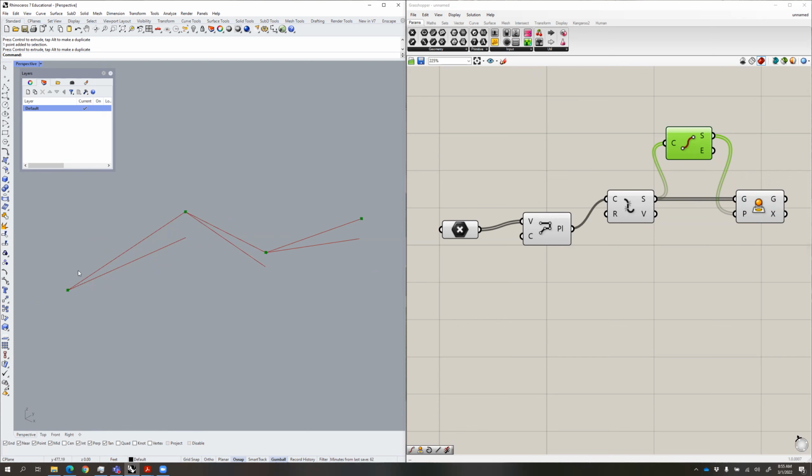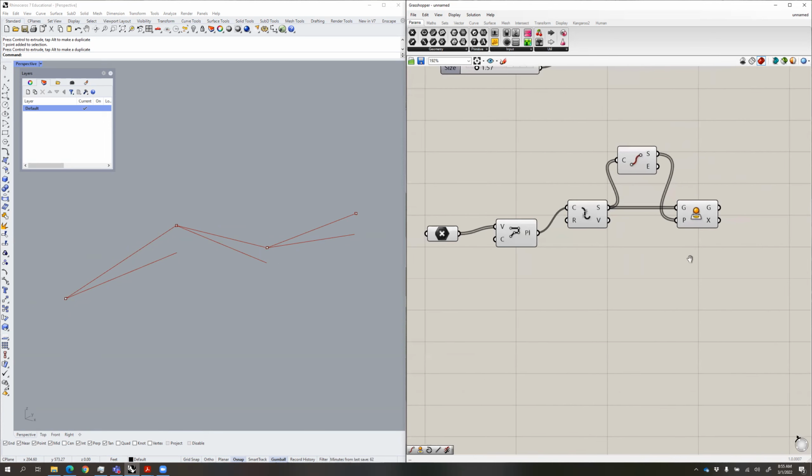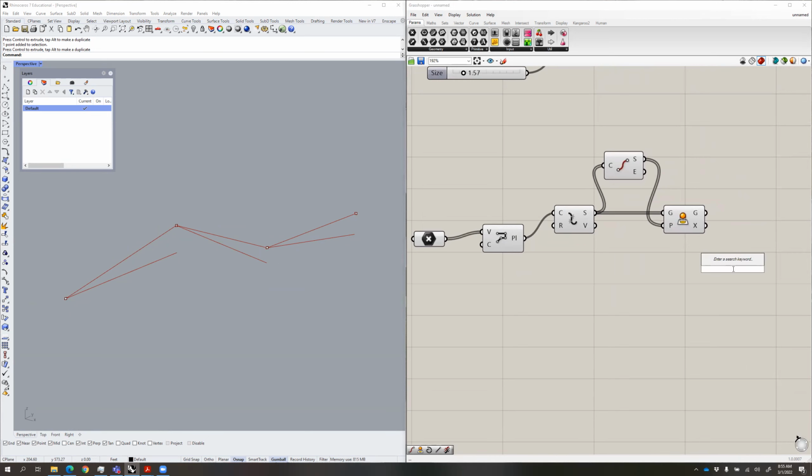It's nice to see the triangle look like a triangle where it's going uphill. So this is kind of what we're doing here. Now that projected line is flat. If I move to the right, you can extract a length. If I type in length in there, there's a thing called length, measure the length of a curve, right? So now this projected curve, if we extract the length of it, we now have the horizontal length of each of those curves projected.